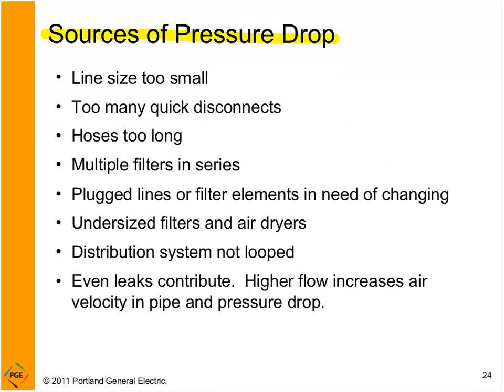And these things can be anywhere between, I got a clogged line. I mean, a 2-inch pipe that's very, very old and has seen water and eventually can rust and corrode up. That'll create a pressure drop. The end uses still need what they need. And if there's a pressure drop in the system, that means I have to jack up the compressor pressure at the source.